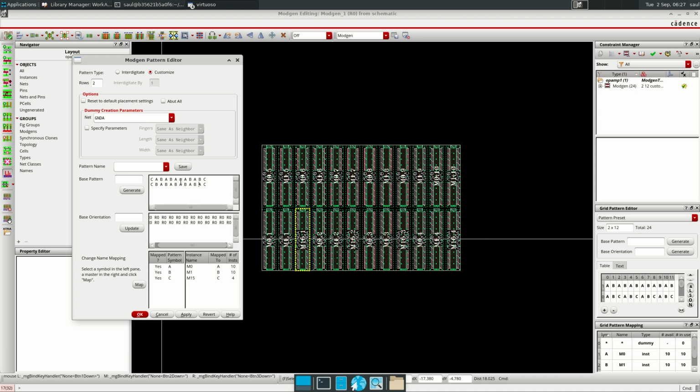So if we have an even number of transistors in each row, there will be a complete transistor on the left and on the right, and we can do the interdigitation exactly as we did it in the lecture. Okay, but this pattern is quite okay. You can see there is a perfect zigzag here. A's and B's are doing a zigzag, and the same number of transistors are on the top and in the bottom. So it is quite a good interdigitized device.